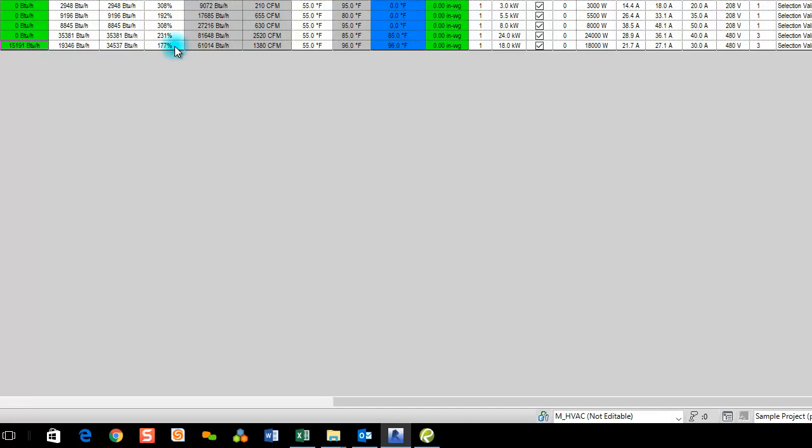The important takeaway from these families is get your connections, get the airflow to the equipment sooner, get your loads into the Revit models sooner. And you guys will see some workflows coming that are just going to make this process look like a joke in regards to getting calculated airflow to your diffusers. And then you're just left with making some duct connections to the unit.